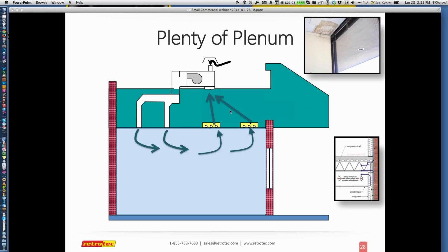The issue here is that this air is running wild up in the upper section, exposed to areas that become outside walls or outside ceilings that are part of the walkway. So I could easily have, with can lights or other penetrations, hot moist air come into these sections. It's now mixed with the conditioned air that I have, along with any water pipes or the ductwork itself that can have a temperature change.